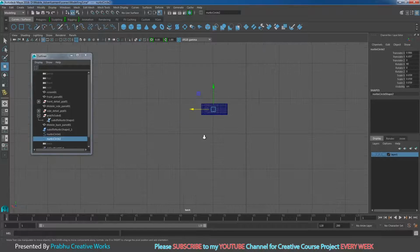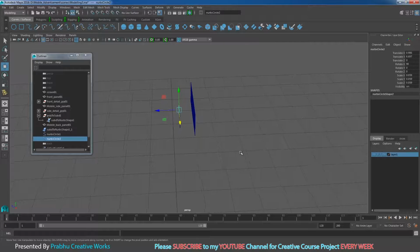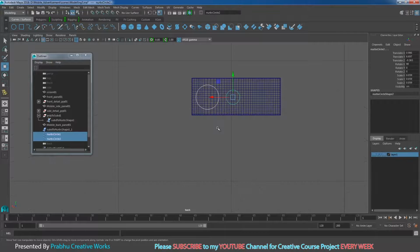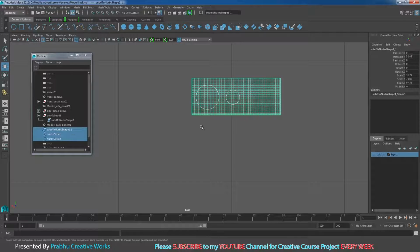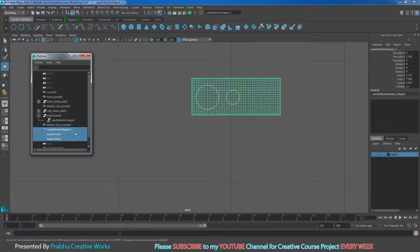So now you are able to see cleanly. Go to perspective, and I will select both curves. You want to move this one in Z, so shift right click and choose back view. When both knob circles are selected, shift select your knob shape: select knob circle 1, control select knob circle 2, and control select the knob shape in the outliner.